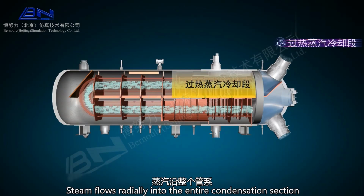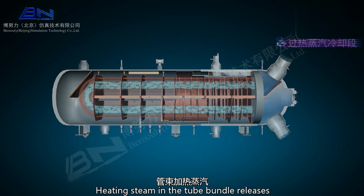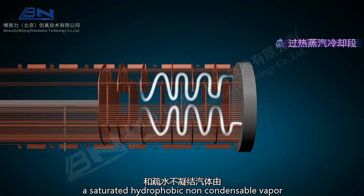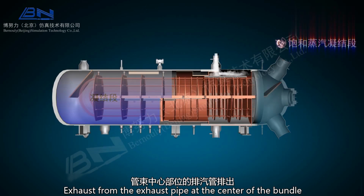Steam flows rapidly into the entire condensation section along the entire piping system. Heating steam in the tube bundle releases a large amount of latent heat of vaporization, and it condenses into saturated drain water. Non-condensable vapor is exhausted from the exhaust pipe at the center of the bundle.